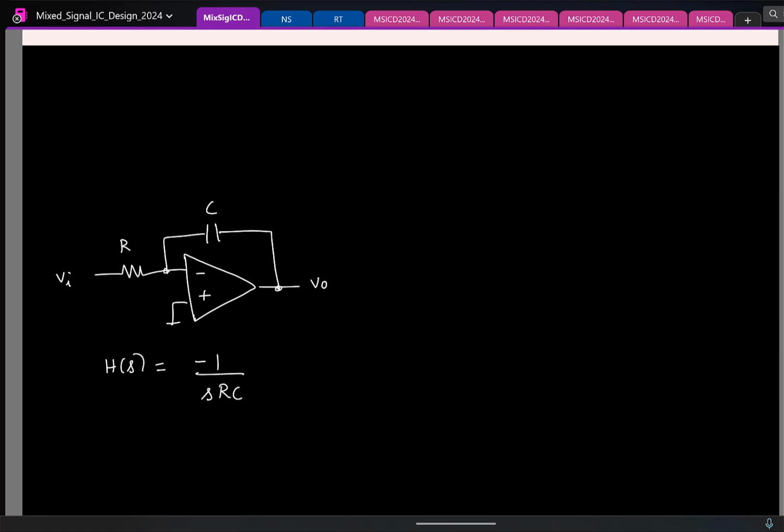So again here you see that, finally this will be used in a big negative feedback loop to realize a filter. But now we can clearly see here the frequency depends on R and C. It will vary. So again the idea is to replace a resistor with a capacitor. So we just saw how to do that. So the thought process is this same thing.